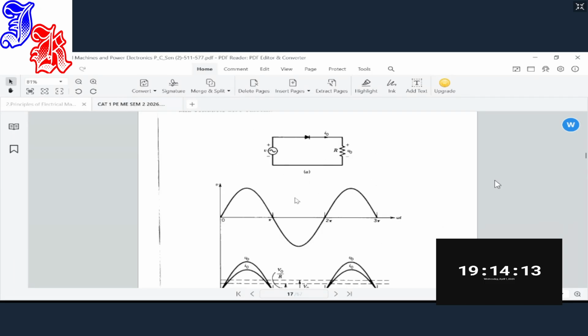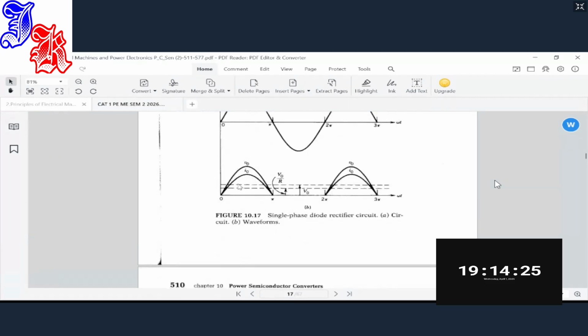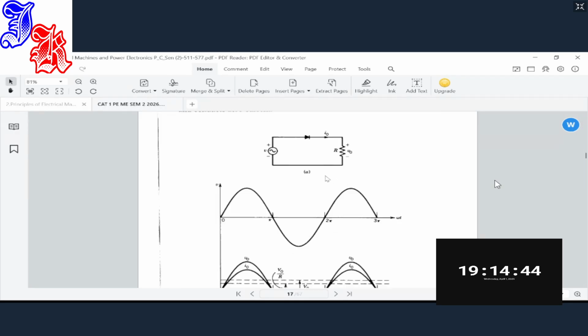connection. So this is an uncontrolled circuit, or we can say it is a half-wave rectifier circuit with the load being only resistive. For a resistive load, you'll find that the curve for voltage and that of current is similar. The only difference is the amplitude, since we normally get the current by dividing voltage by the resistance. So the rest is the same. Yeah, that is a half-wave rectification using a diode, or uncontrolled half-wave rectification.